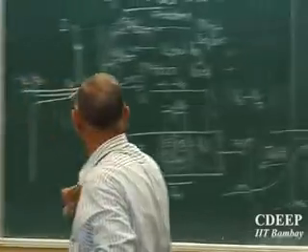There is no space charge, it is neutral, right? But that means these additional injected carriers do disturb the neutrality in a very small way, creating some built-in fields in the neutral region, which actually pull the carriers towards the end of the contact. This is very important. This is a paradox: you keep telling E is 0 in calculation, and suddenly you say, if E is 0, how do I get the carriers? Okay, don't worry. I say, a very small field, treat its value as 0, but it will take the carriers. This is something all ideality people do, and that's what I will also do.